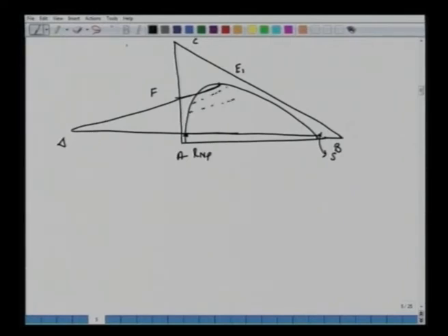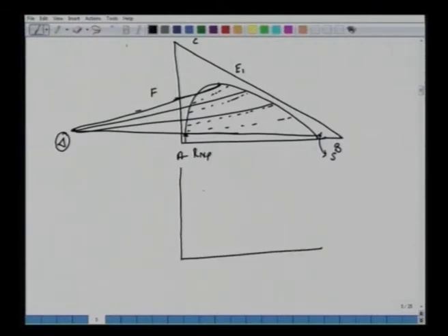So the first thing is to find out that tie line which, extended, will pass through or intersect this R and P, S. In other words, to find out the del R min in this case, all we have to do is, if we have a curve like this and this is F here, we have located S, we have located R and P, and we have extended this line here. We are looking for del min. What is the minimum amount of solvent when the operating line coincides with the tie line.